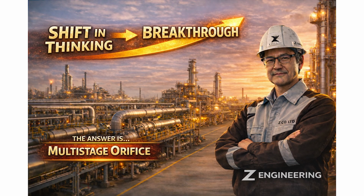There is one important point. A multi-stage trap is not simply an improved single orifice trap. It is a completely different design philosophy. The way pressure is handled is fundamentally different. Single orifice traps have a physical limitation. Multi-stage traps overcome that limitation through a new concept and a new structure. This is the key point to understand.